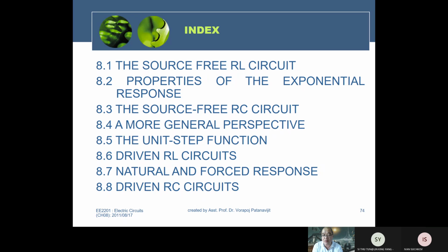If the circuit contains only the resistor, the current and the voltage will suddenly drop to 0 immediately. But if the circuit contains an inductor and a capacitor, the current and the voltage will gradually drop, because the inductor and the capacitor have some energy. The capacitor and the inductor perform like a battery for a short time. They try to maintain the current iL, or the voltage vC, okay?